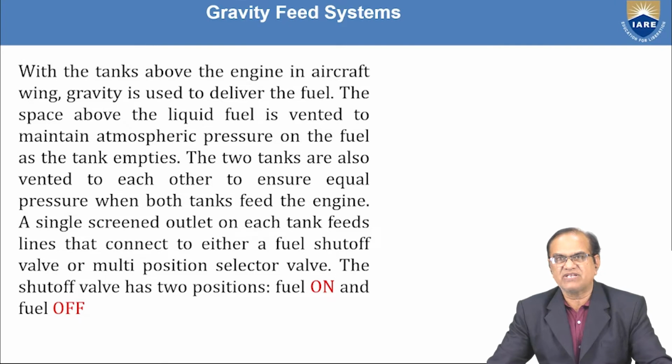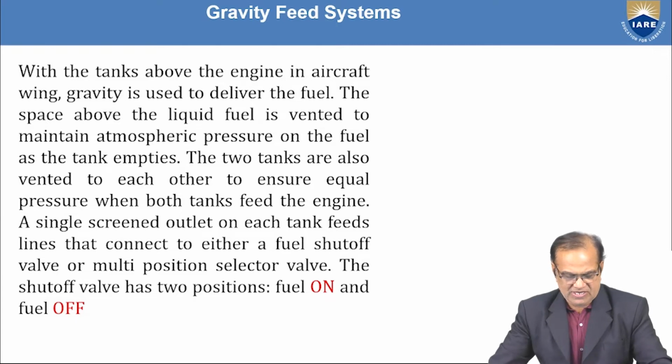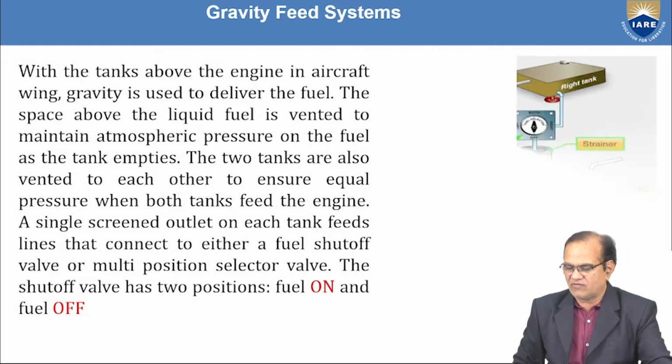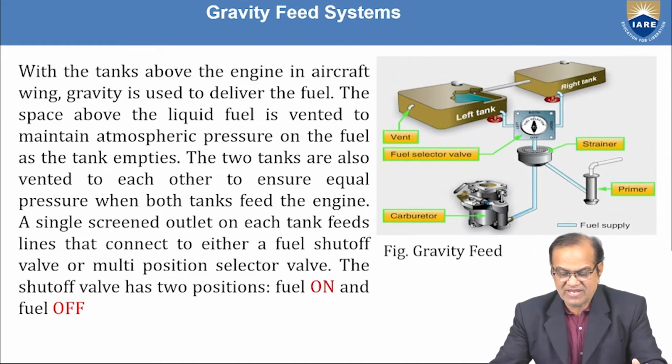A single screen out on each tank feeds lines that connect to either a fuel shut-off valve or a multi-position selector valve. The shut-off valve has two positions, fuel on and fuel off. So here you can see a very basic system.